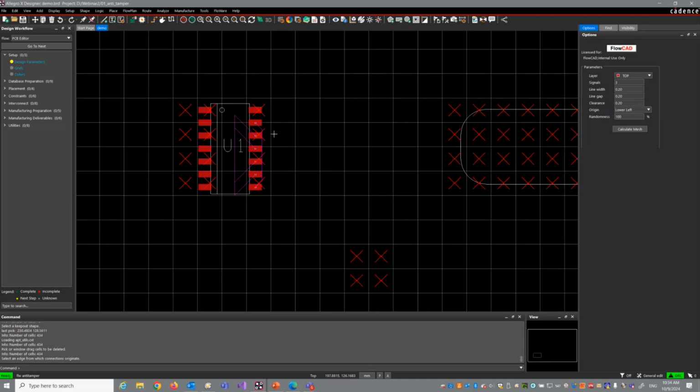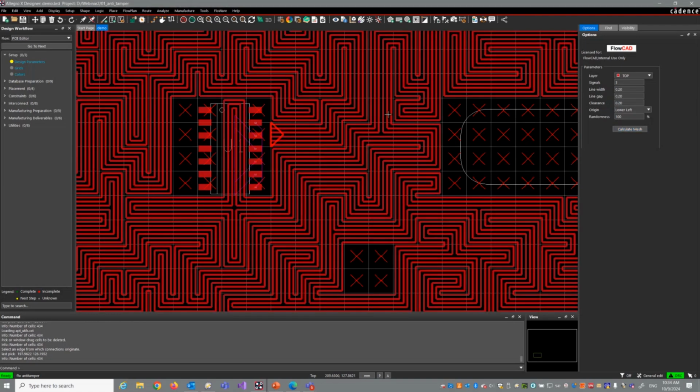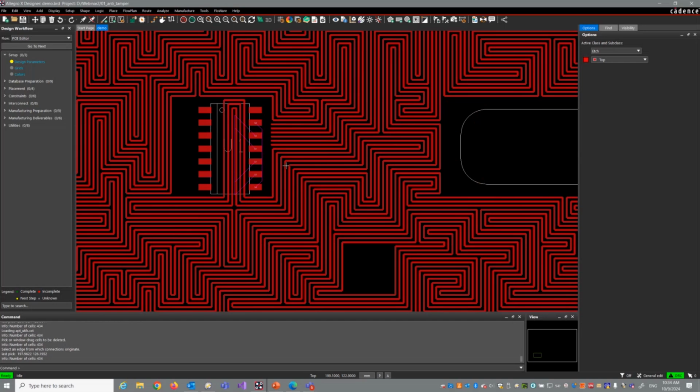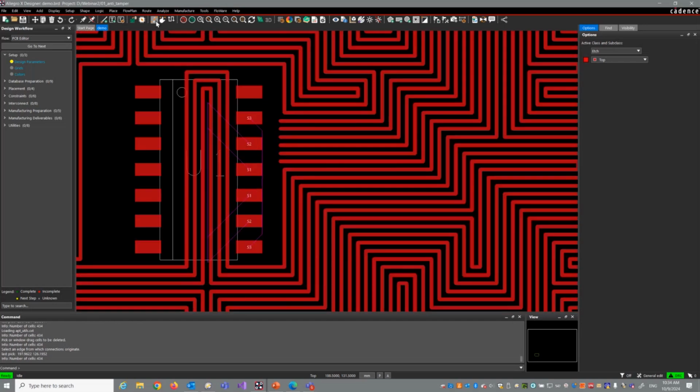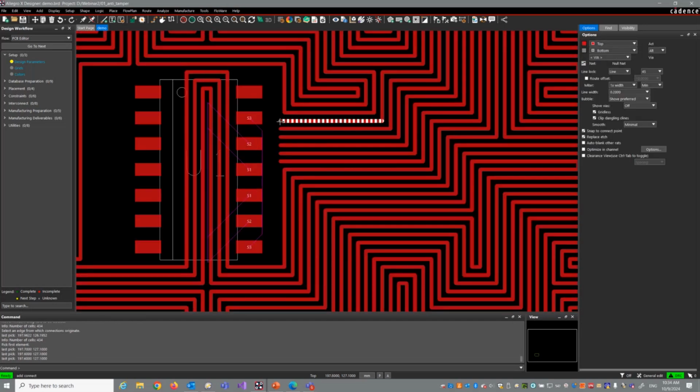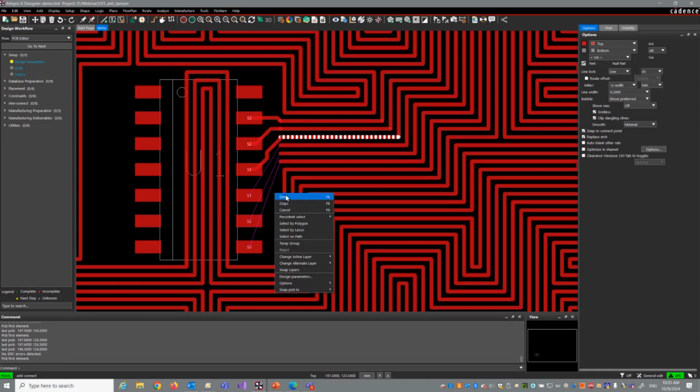And next, you specify the starting point. Select starting edge. You say, I want to start here. And then all you have to do is simply press calculate mesh, and then the signals will get generated. Now I'm fine. I'm now routing the nets. For example, this one here is still not connected. And now you see that the 3 signal loops have been connected properly.